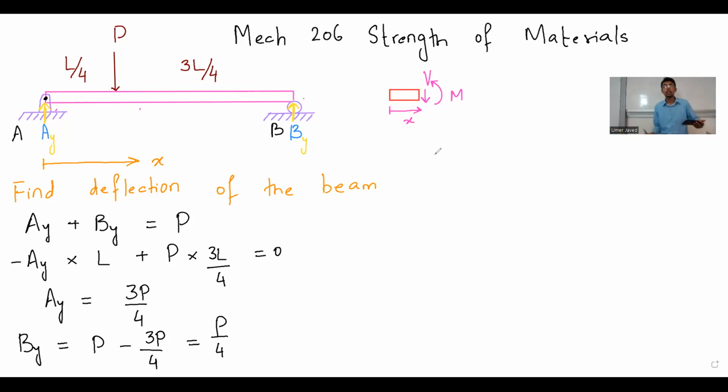What you have to understand is that the bending moment before the P and the bending moment after the P will be different, right? I hope you remember that. So you cannot just straightforwardly do this problem. When you are trying to integrate, do you remember that integration that we were doing last time? I hope it rings bells. When you were performing that integration, you had to utilize that bending moment, right? But now you will have bending moment before the P and bending moment even after the P.